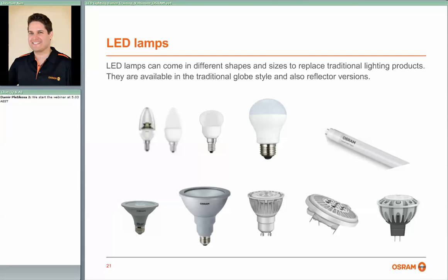So how does the fitting the lamp is going into, bear with me, affect its lifespan? That's a good question. With a lot of these LED products, we as a manufacturer have a recommended ambient temperature range, and we also state on a lot of these products what the maximum TC point is.